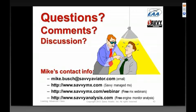Okay, George is wondering. And again, it's not just Cirruses. I mean, a lot of airplanes are flying around with JPI engine monitors or Insight GEMs that have a lean find mode or whatever they call it. Different monitors call it different things. And again, I consider it to be a bad idea to use those features. I don't use them myself, and I teach my clients to avoid using those, again, because to use them you have to spend a lot of time in a place that doesn't make the engine very happy.